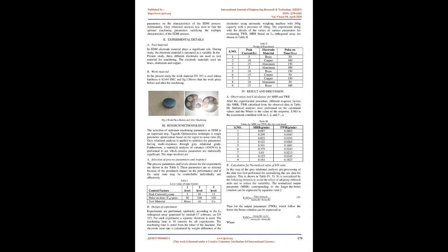Using PCA-based Gray relational analysis has been selected. The original Taguchi method was designed to optimize only a single performance characteristic, whereas the Gray relational analysis has been proved to effectively resolve the complicated interrelationships among multiple performance characteristics of the EDM process.